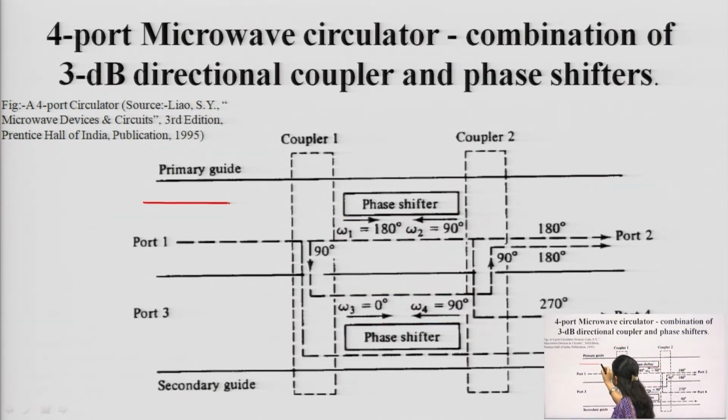What happened to that signal? There is a chance the signal goes this way and some of it gets leaked like this. So, we have to check both signals, and as per the principle of the circulator, if we provide the signal at port 1, it will go to port 2. So, let us see how it is working. First of all, we will check this signal.